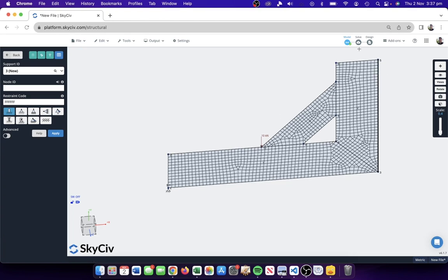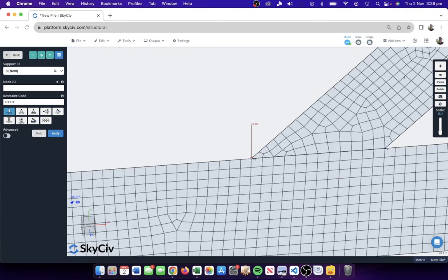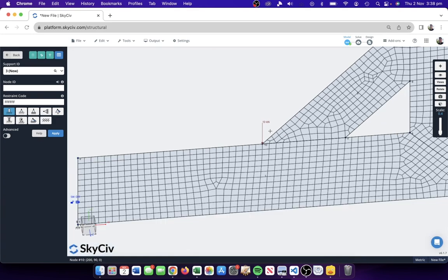And another issue which we might have noticed is that there was a very, very concentrated stress here, because that's where the load was being applied, where in reality that's probably not going to be concentrated to a specific small point on the structure. Very rarely will you have a contact load at a really finite position on the model. You'll usually have it spread over a contact point on a bracket or a plate.